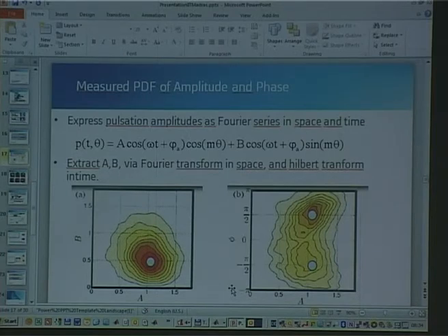So I've shown these modes, and basically you can see them at every instant of time as 2 rotating modes going in opposite directions with different amplitudes, or you can see it as 2 standing waves, each with its amplitude, one with more like a cosine distribution around the circumference, the other more like a sine distribution. And they have a time varying amplitude which varies sinusoidally. I didn't put it in the grid, but basically this amplitude A of this mode and this amplitude B also change in time, but much more slowly than the acoustic time.